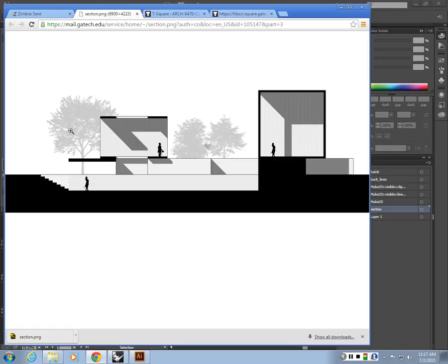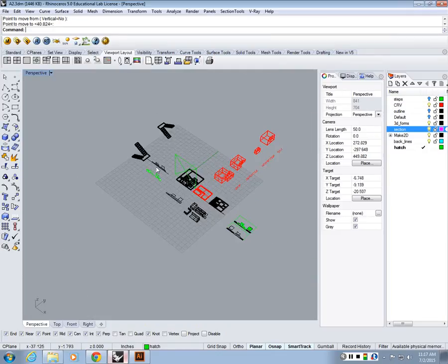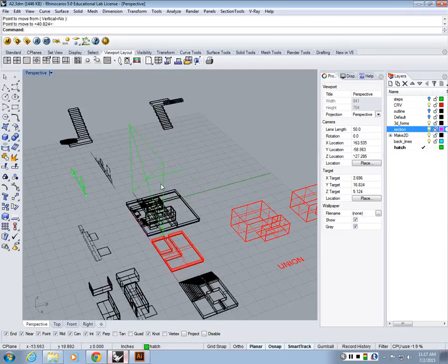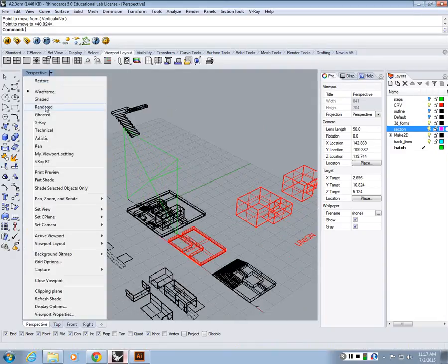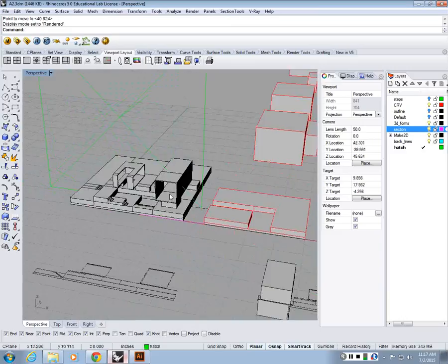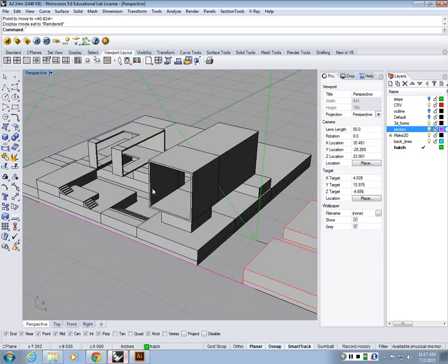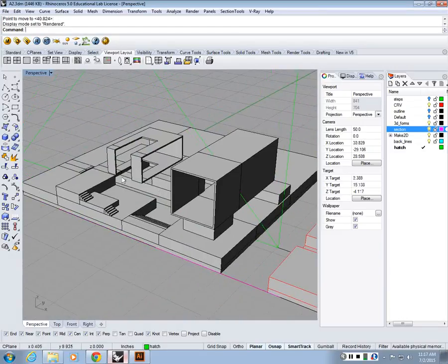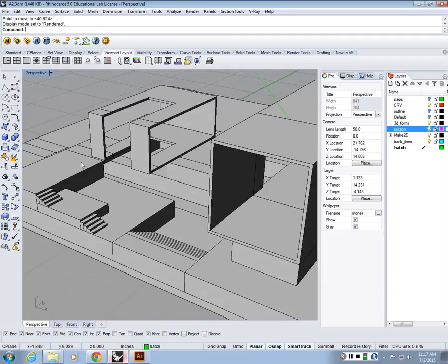in the background. And the shadow though, I actually spent some time yesterday trying to streamline how to get shadows easily from Rhino, because in these viewports, when you render the view, you can see that we have some preliminary shading happening. You guys see that? This surface is shaded differently than this surface, although they're the same material.